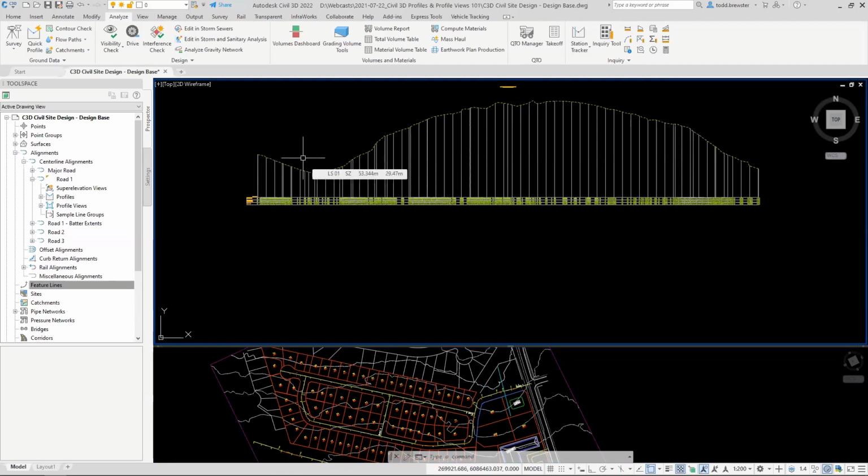Now, in terms of alignment profile creation, there's actually a couple of ways you can do it. You can do it IP-based, drop in new points where you want to create points of inflection. You can do it by element, and you can do it based on best fit entities. So I'm going to do the basic IP creation, probably, which I'm going to guess most people would typically use. By element is a bit more advanced and is not going to be covered in this session. But the idea of that one would be if there's certain points where you know you need a curve to appear or an IP to happen, you can draft all that in first and then connect everything up in between it.